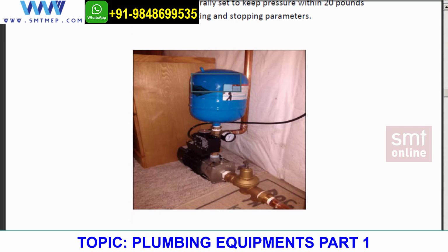So it will be half filled, and we need to calculate this as per the pump inlet and outlet, or the cut-in and cut-off of the pump. We need to design this also. Generally you'll see pressure tanks from the manufacturer in 50 liters, 100 liters, 200 liters, 300 liters, 500 liters. I'm talking about residential and commercial. It might go to 3000 liters also.